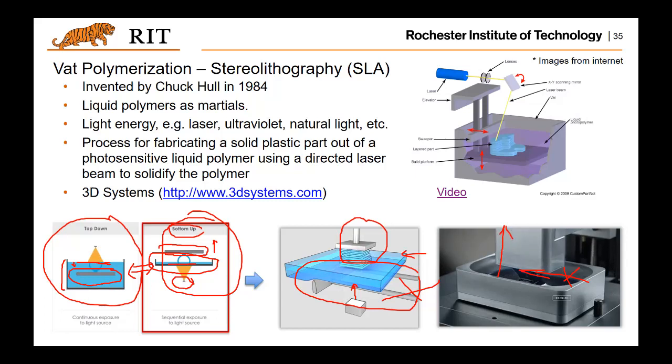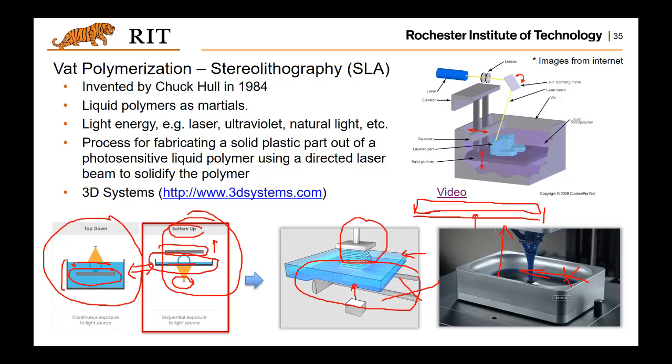So how do they achieve it? I will definitely introduce the details, but let me draw what they do. So this is the bottom of the tank, all right? And this is the resin in the tank, all right? It turns out they managed to have a so-called dead zone, or an actual layer of oxygen, to prevent the touch of the resin and the bottom of the tank.